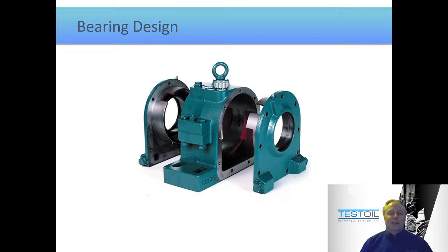It's not the bearing, it's an exploded view from the manufacturer, so you can see things a bit more clearly. But you can see where the 5 gallons of oil goes inside the bearing housing, but you can also see at the top edge on both sides a Zerk fitting for where the grease goes to grease the seals. And so in effect, probably what happened with this bearing is it was over-greased. Over-greasing the seals blew out the seals, therefore a little bit of grease migrated into the oil. That didn't cause the catastrophic failure. What did, though, was the lack of seal now. Because the seals were compromised, this dirty, dusty environment was allowed to get into the bearing and caused extensive abrasive wear and eventually wiped the bearing.